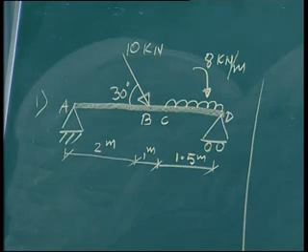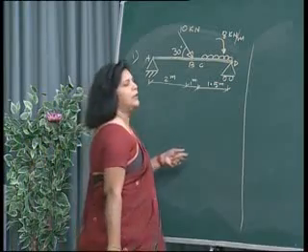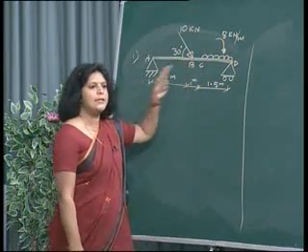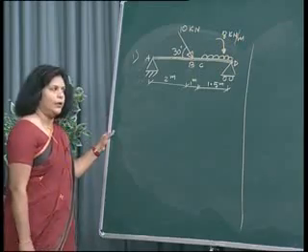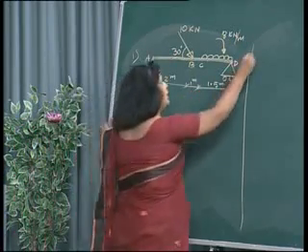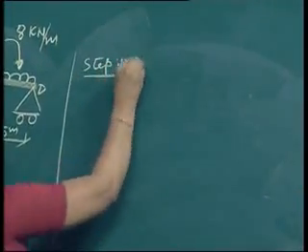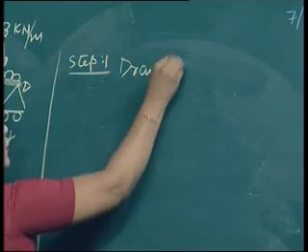To draw it, first of all, we have to convert our load intensities into concentrated loads. So step 1, draw the free body diagram.